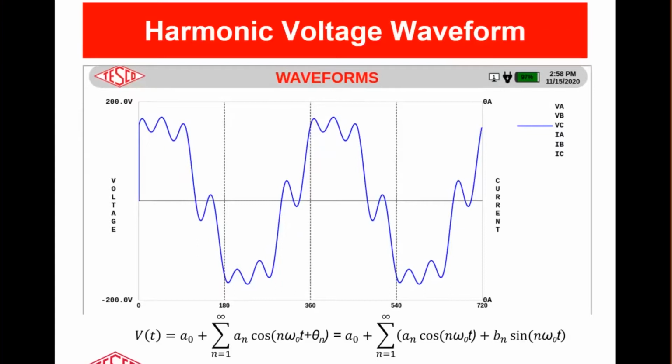When we get harmonics, we get frequencies that are multiples of 60 hertz, or at least we can analyze them as multiples of 60 hertz. We represent those complex waveforms by the sum of a whole bunch of 60 hertz, 120 hertz, multiples of the 60 hertz fundamental waveform.